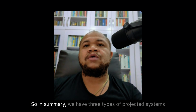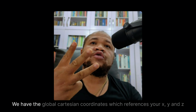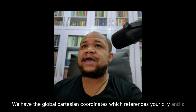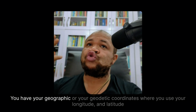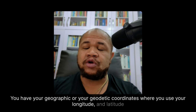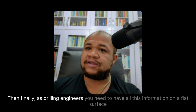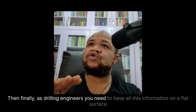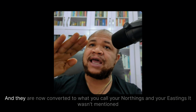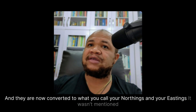So in summary, we have three types of coordinate systems. We have the global Cartesian coordinates, which reference your x, y, and z. You have your geographic or geodetic coordinates, where you use your longitude and latitude. Then finally, as drilling engineers, you need to have all this information on a flat surface, and they are now converted to what you call your northings and your eastings.